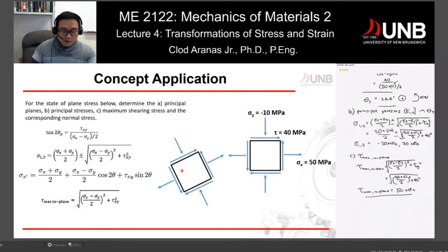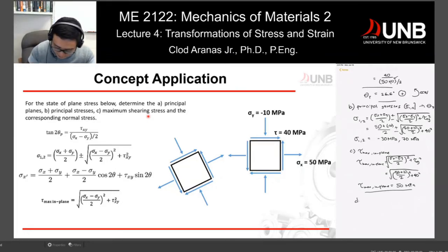So how can you determine the corresponding normal stress when we reach the maximum shearing stress? Again, these are different things. One is the principal normal stress. Another is a different rotation, for the maximum shearing stress, and they are 45 degrees apart in terms of angle, but you can easily calculate it in terms of equation.